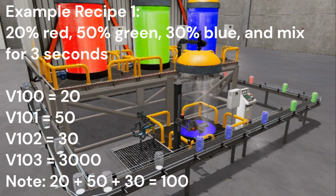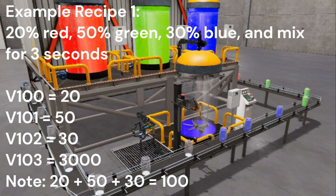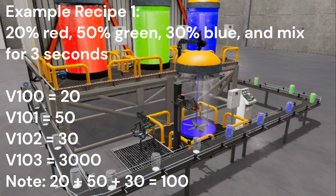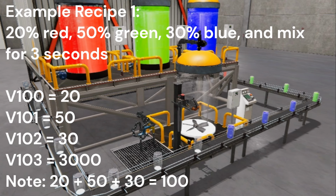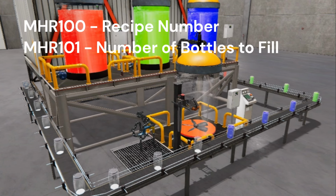Example, if we want 20% red, 50% green, 30% blue, and mix for 3 seconds, here are the settings for the first recipe. V100 equals 20. V101 equals 50. V102 equals 30. V103 equals 3000, expressed as milliseconds for the mixing. We will use address MHR100 for the recipe number and MHR101 for the number of bottles to fill.